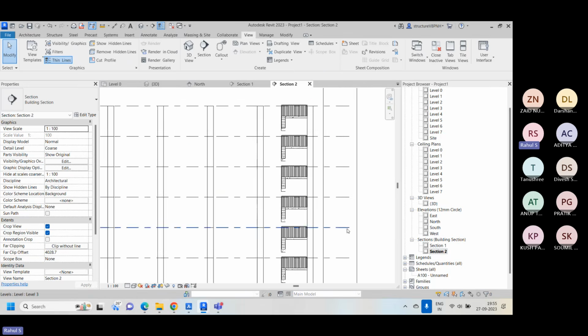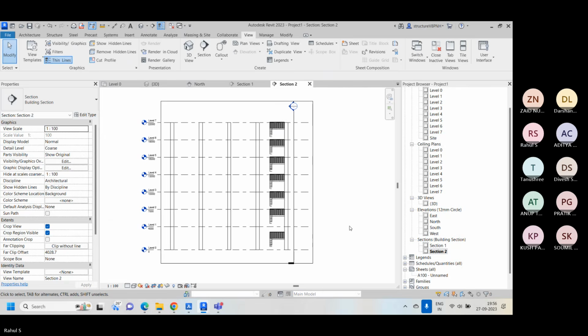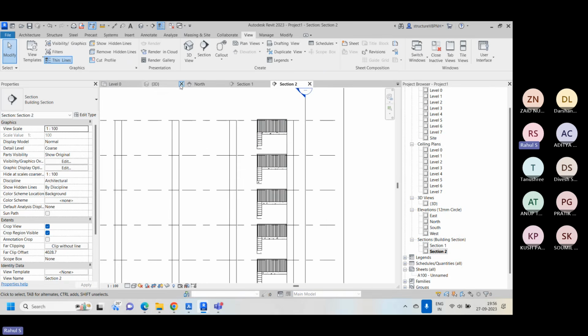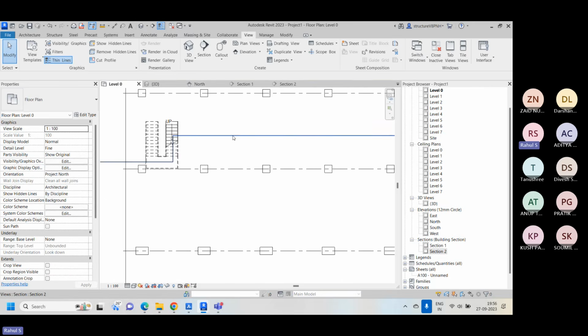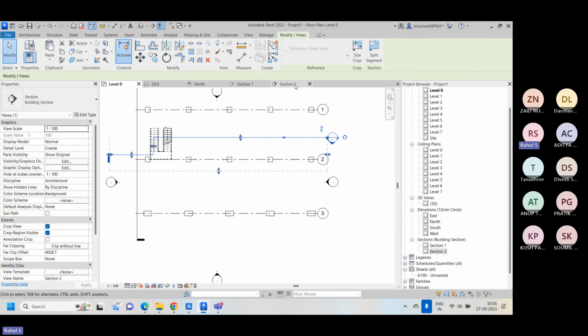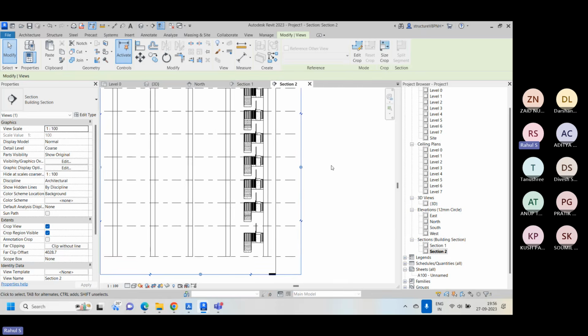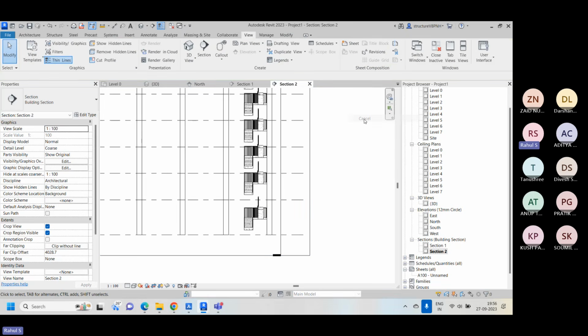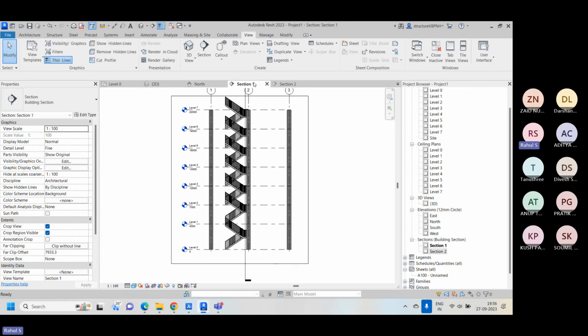See this. If you adjust the section, let's say here, or just create it like this, the section automatically gets updated. Now you can see the changes. So basically you can easily generate multiple sections. It's not limited to one or two. If you want to generate 1,000 sections for one view, that is also possible, you can easily create them.